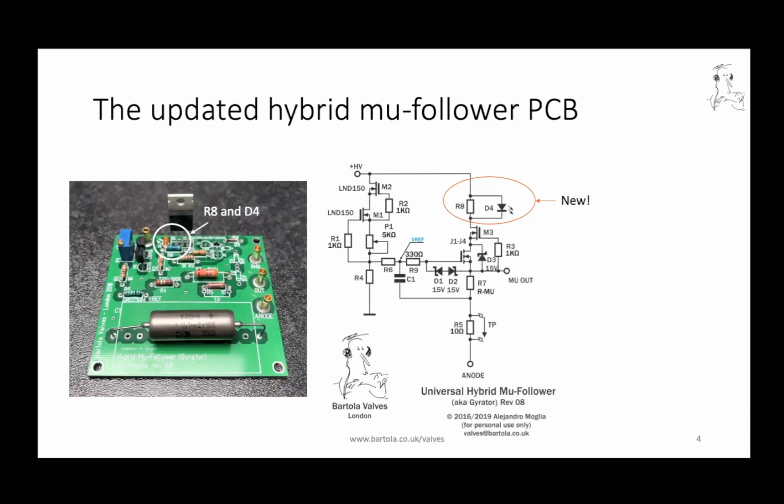It's reduced to less than an ohm, so you wouldn't be worried about that. I have measured it. I have used it. I haven't even heard any impact of the addition of that resistor. Don't forget it's on the drain side, so that resistance gets divided by the transconductance when it's reflected to the source side. So it's in a position that doesn't affect.